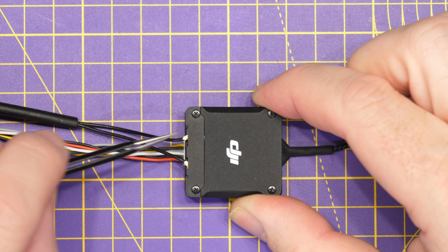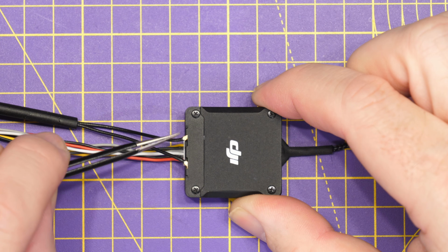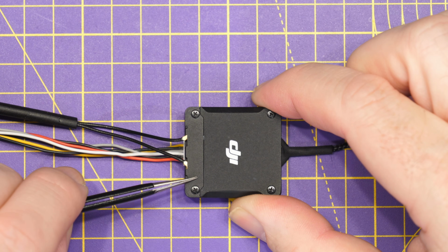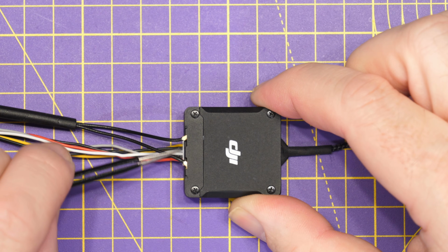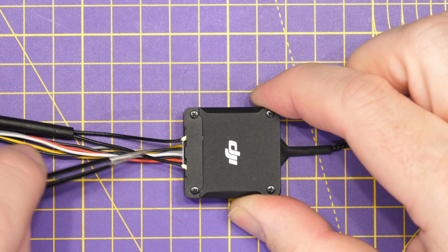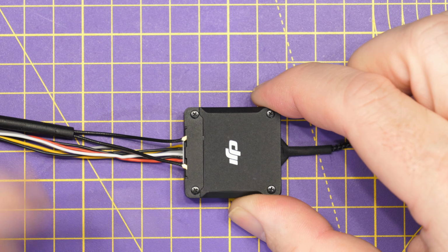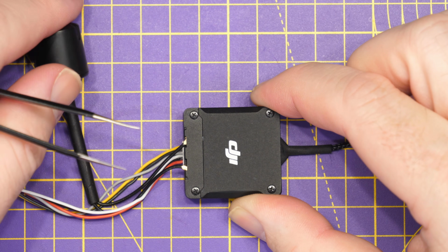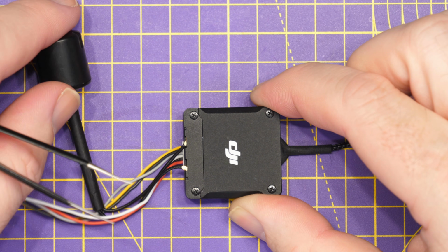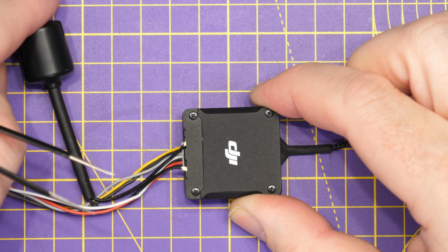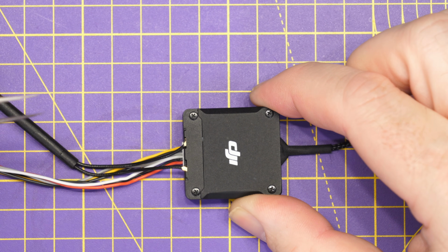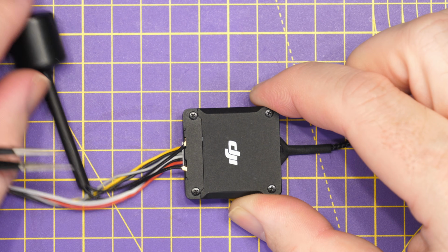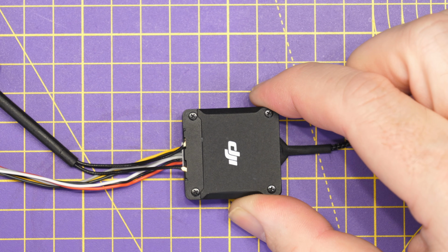It's very unlikely for the antennas to just come unplugged on O3 because they do have this plate that goes over the top, but it is possible to damage the cables around here if you were forcing them through a frame. Obviously, if everything looks good, the other thing I would suggest is just giving the antenna a little bit of a shake to make sure that there's nothing inside that rattles. And if you're still having problems at that point, I would suggest swapping this antenna for maybe some standard ones and then seeing how it performs.